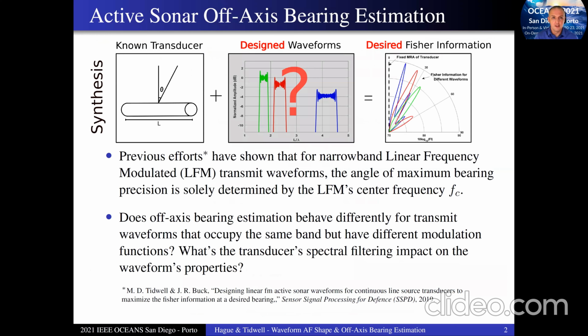Now, the main theme of this work is about active sonar off-axis bearing estimation, and the principle behind off-axis bearing estimation is that if you have a projector transducer with a known beam pattern and you transmit waveforms with a known spectrum, you can actually control the angle at which the Fisher information for the target bearing estimate is maximized. Moreover, you can do this without shifting or moving the main response axis of the transducer itself.